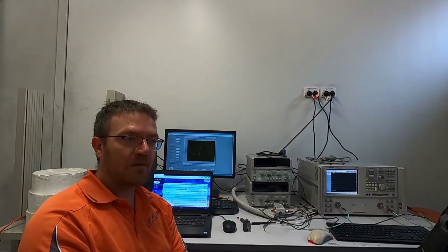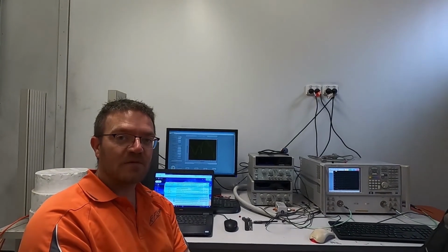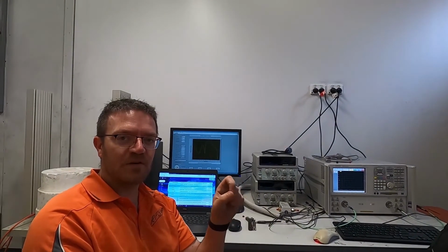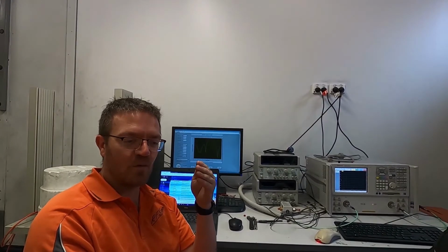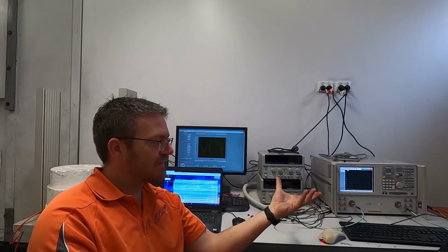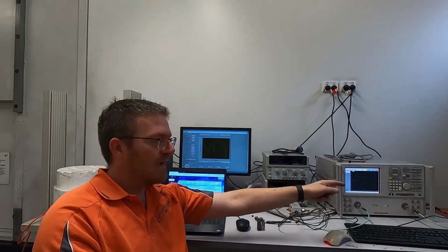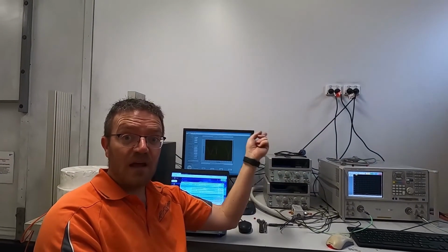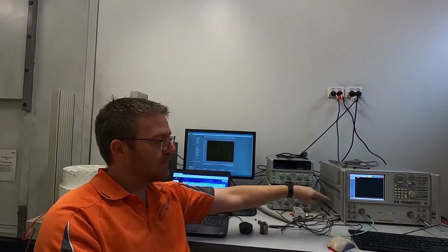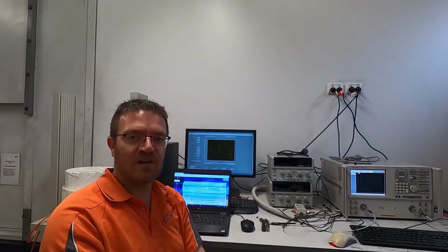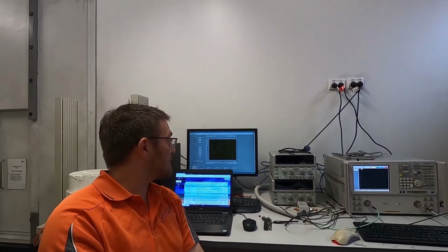Now S parameter in our RF world is the coupling matrix or coupling numbers. So S21 means you try to see how much energy goes from port 1 to port 2. In this case we send the signal to the back of the chamber to an antenna, and we see how much energy comes back through the other port, and I'll show you on the inside what it actually means. It makes more sense when you see the whole setup. So when the measurement is done, I'll show you the inside.